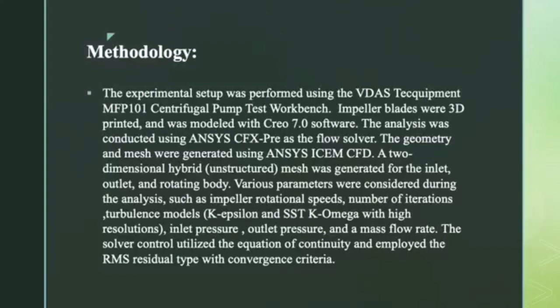Various parameters were considered during the analysis such as impeller rotational speeds, number of iterations, turbulence models, inlet pressure, outlet pressure, and mass flow rate. The solver control utilized the equation of continuity and employed the RMS residual type with convergence criteria.